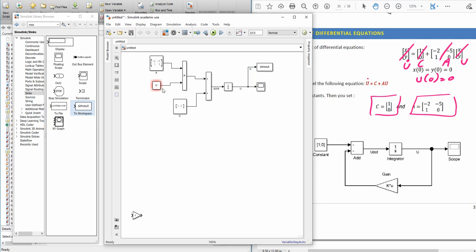Now before running the example, running the simulink system, remember that we don't have the u value, so I will delete it from here. Let me delete the bus, and the u value should be taken from here. So I will press Control, take from the mouse, connect back to here, and then you can resize it like this, guys. Okay, double click here to show you that this is the value of u.